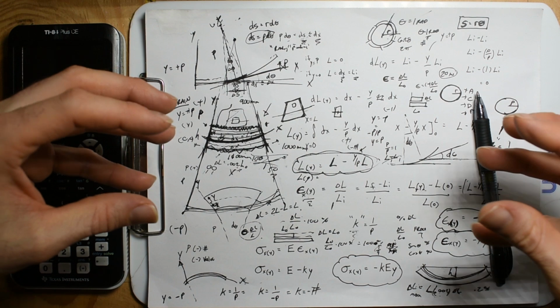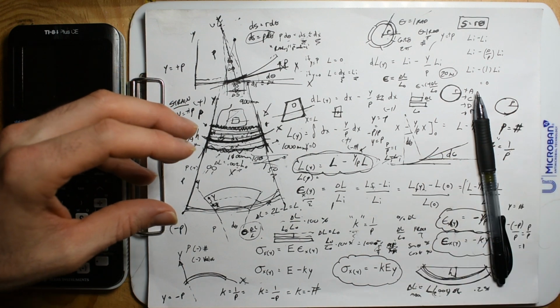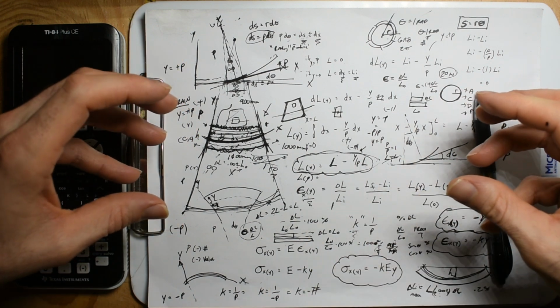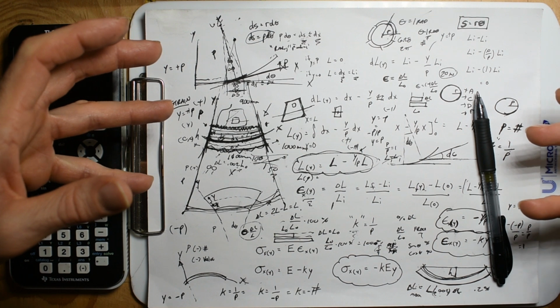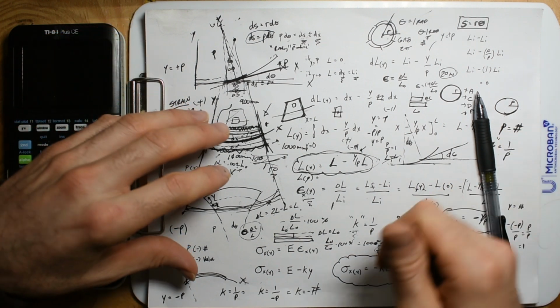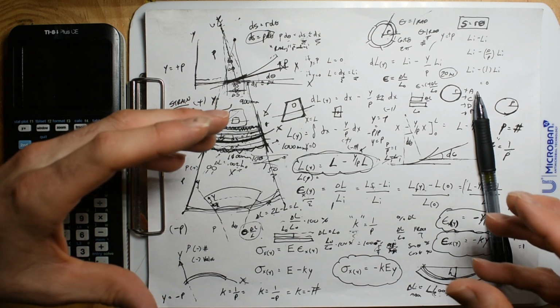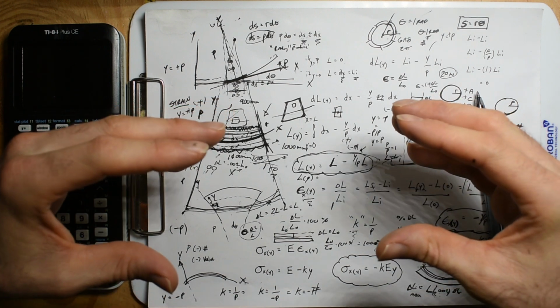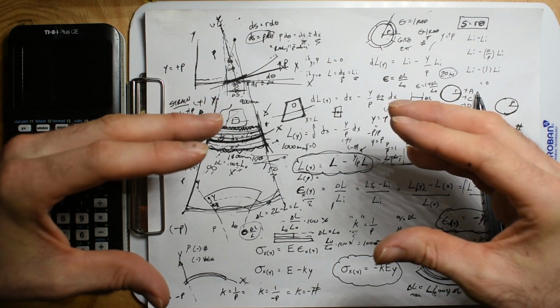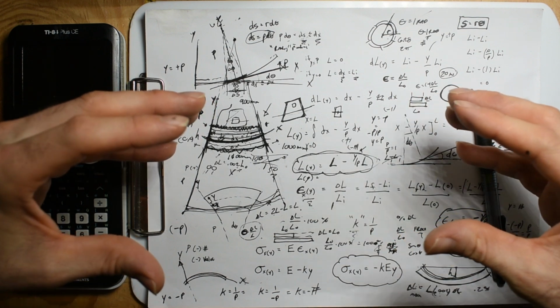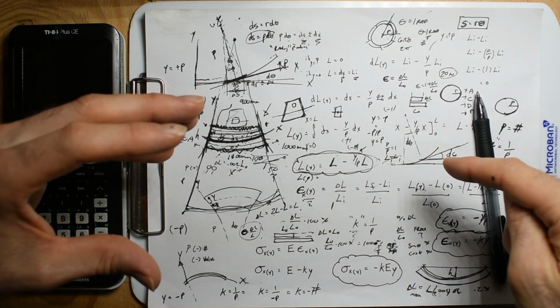So if I have a bar with an area of 1 square inch, 1 inch by 1 inch steel bar, pretty heavy duty, I can put 58,000 pounds on it. I could hoist a semi-truck with it. And a 1 meter steel bar is going to stretch 2 millimeters if I do put 58,000 pounds on it.